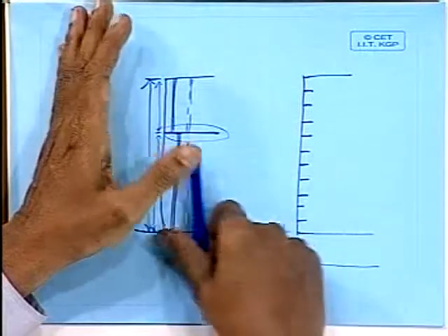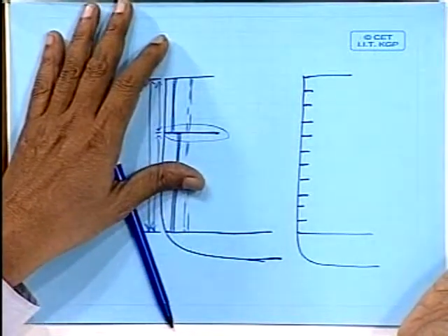In a longitudinally framed ship, these are designed first, and then the transverse stiffening is designed based on the longitudinal strength. And the inverse is the case in transverse framing. Do you understand? I give you another example, a very interesting example many designers face in a design office.